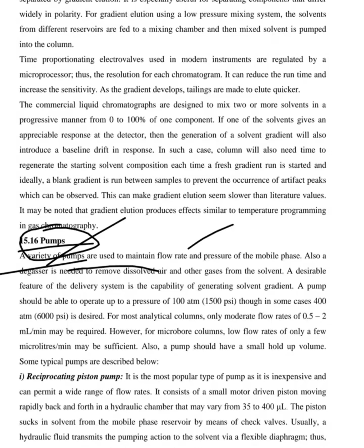It is also used in the degasser, needed to remove the dissolved air and gases present in the solvent. So pumps can create pressures of 100 to 400 atmospheres. Further, there are different types of pumps present.